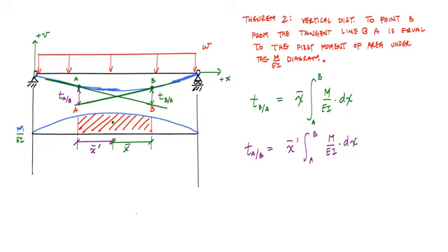Now this is really useful in calculating the vertical displacement at different points along the length of the beam, and you don't really have to apply the integral. Normally the moment or curvature diagram is geometry friendly enough that you can just break it up into areas, multiply each by the distance to the centroid of that area, and sum them all up. For the rest of this video I'm going to explain where this comes from, because some of you may not believe it. In order to explain, let's take a closer look at this AB.